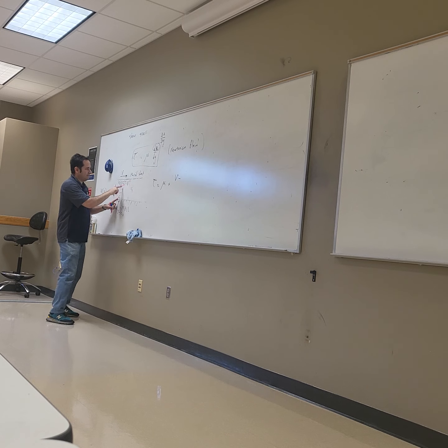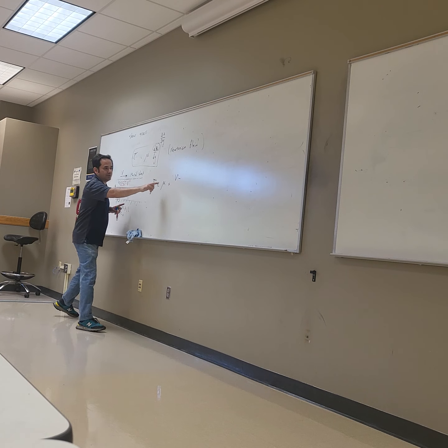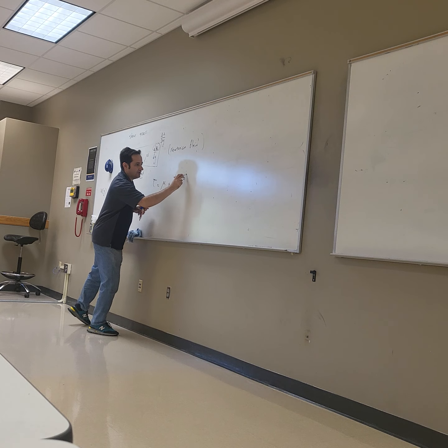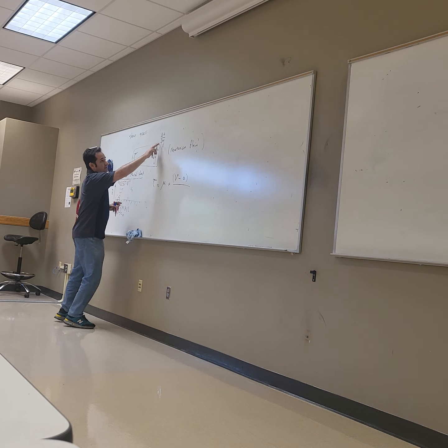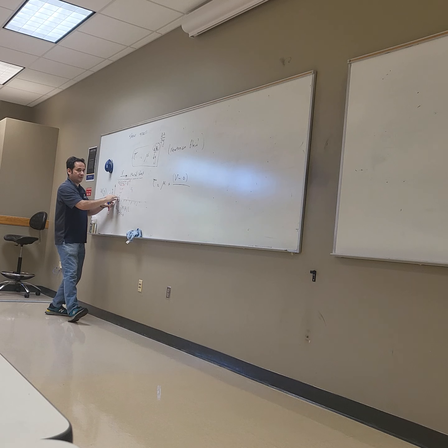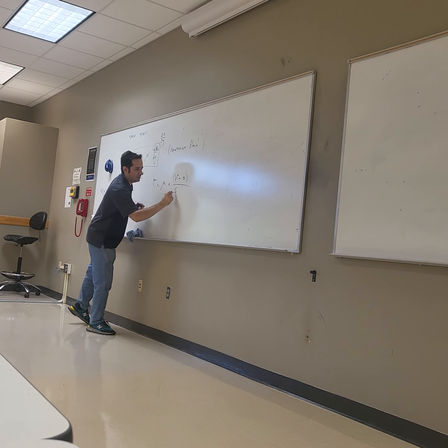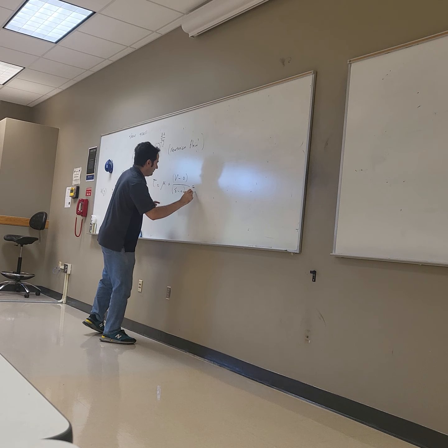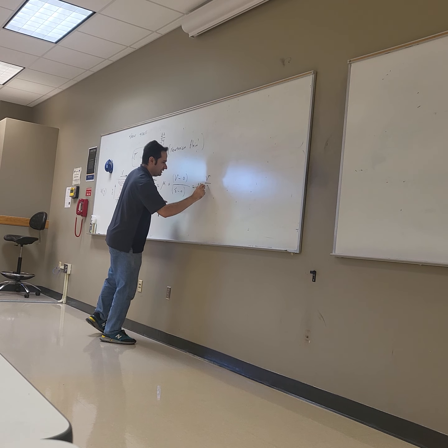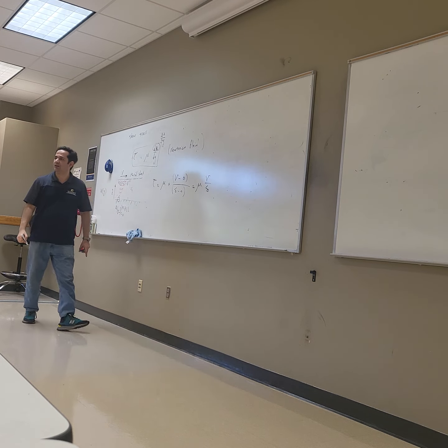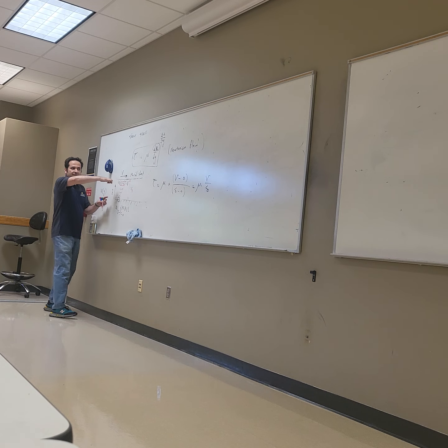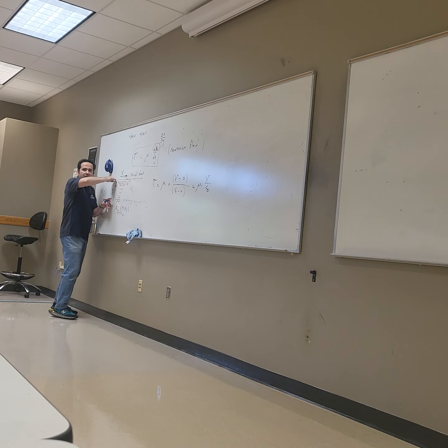So delta u is the velocity here, which is capital V, minus the velocity at y equals 0, which is 0, divided by delta y. The y here is delta minus y at the wall, which is 0. So we can approximate it as mu V over delta. That's the shear, the shear that you need to pull this metal sheet to the right.